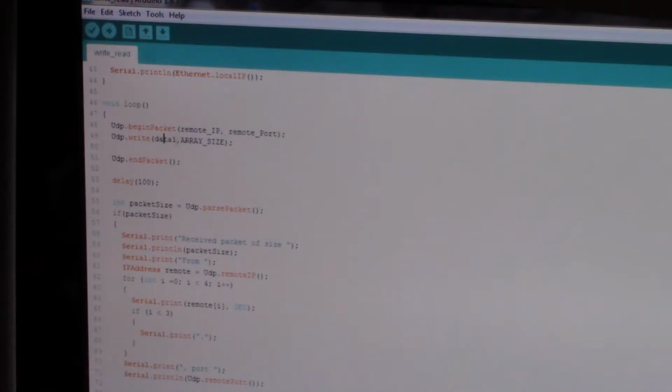This is the data, which is 32 bytes, which could be larger or smaller depending on your application. The most I could get using the Arduino Uno is 700. Possibly if I didn't use an array, I would not use as much memory, and I could probably get more than 700. The packets for Ethernet are about 1400 bytes, probably the biggest you can send over. So this is a relatively small one.